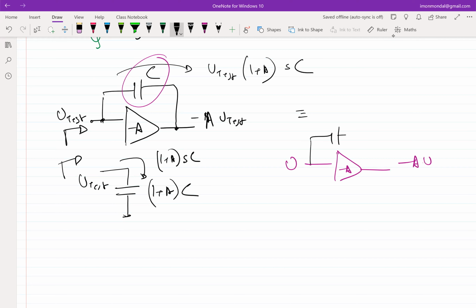And even if I apply this C, this should be minus A times V. That's what a voltage source means. Whatever I connect, it shouldn't change. So this ideally is not possible, but is it possible under some approximate circumstances? That's what we are again after, right? So as it turns out, it's possible. I will show you the math, and then we'll see why it's possible.